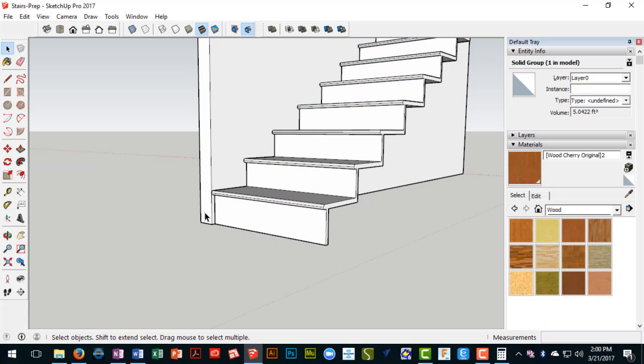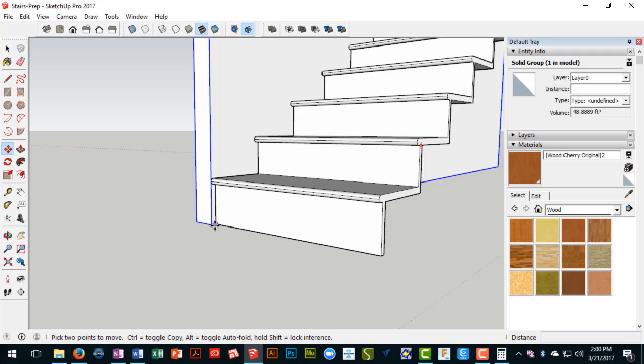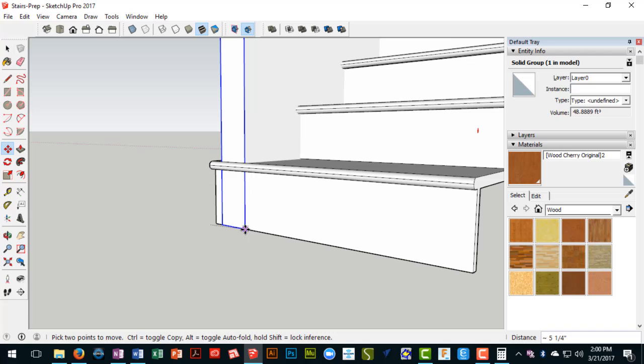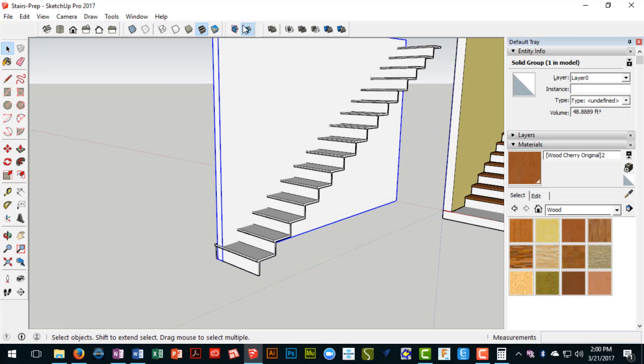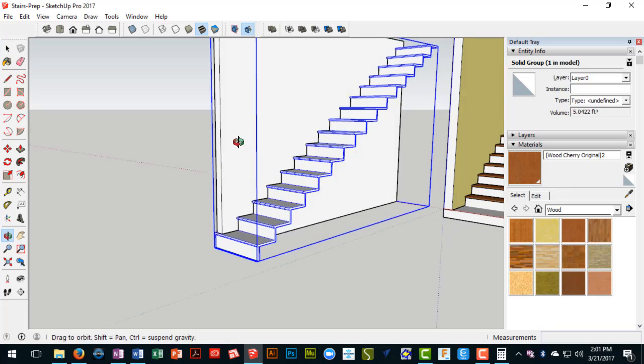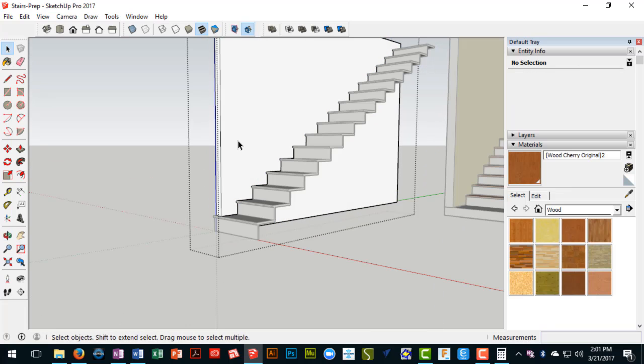So first we're going to overlap them. So I'm going to bring this wall, doesn't really matter exactly where, I'll bring it inside the staircase. And then I'm going to use my Trim Solid tool. So I'll click on Trim. Now if you have something selected, that's essentially your first selection in the trim process. So I'm going to deselect that first. Click on Trim. Select the stairs first, and then the wall, and then press spacebar. We're done. So now I'm going to double click on the wall.